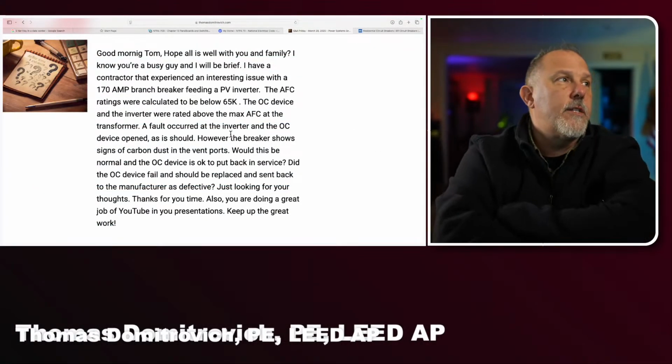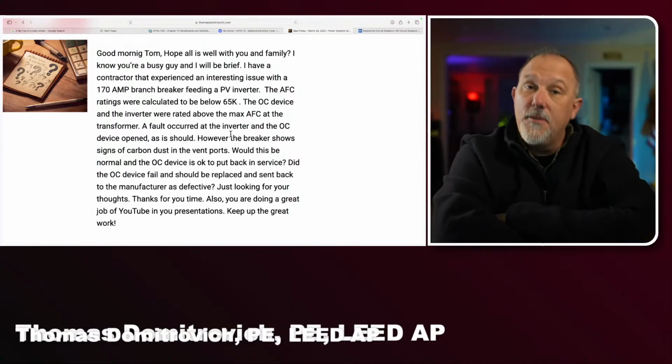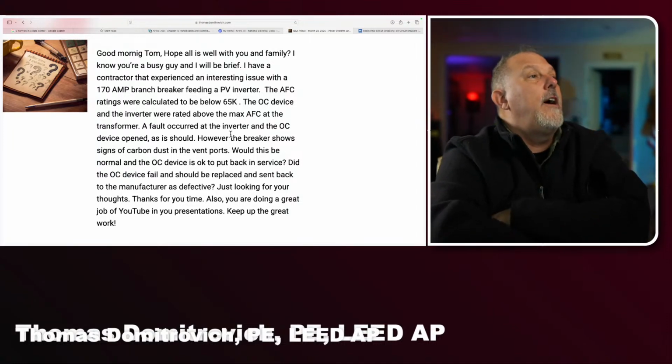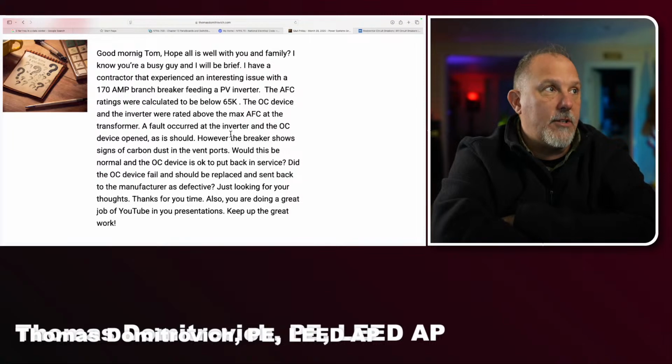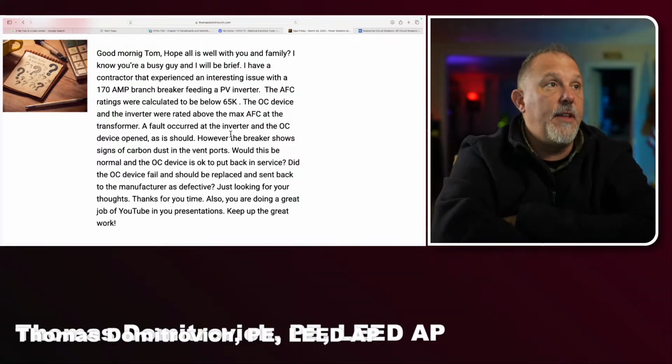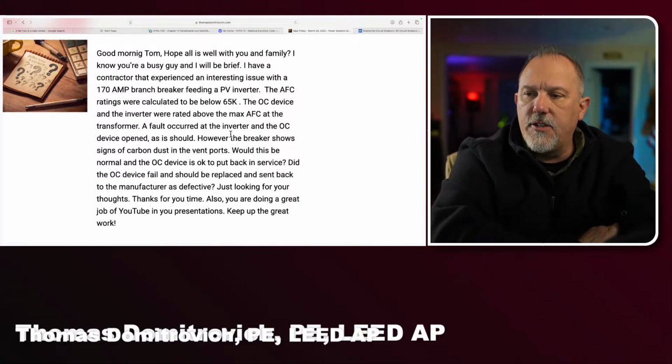There it is. So, this gentleman says, "Good morning, Tom." Good morning. It is afternoon. "Hope all is well with you and your family. I know you're a busy guy, and I'll be brief. I have a contractor that experienced an interesting issue with a 170 amp branch breaker feeding a PV inverter. The available fault current ratings were calculated to be below 65,000 amps. The overcurrent device and the inverter were rated above the maximum available fault current at the transformer." All right, so that means all of our equipment is within its ratings.